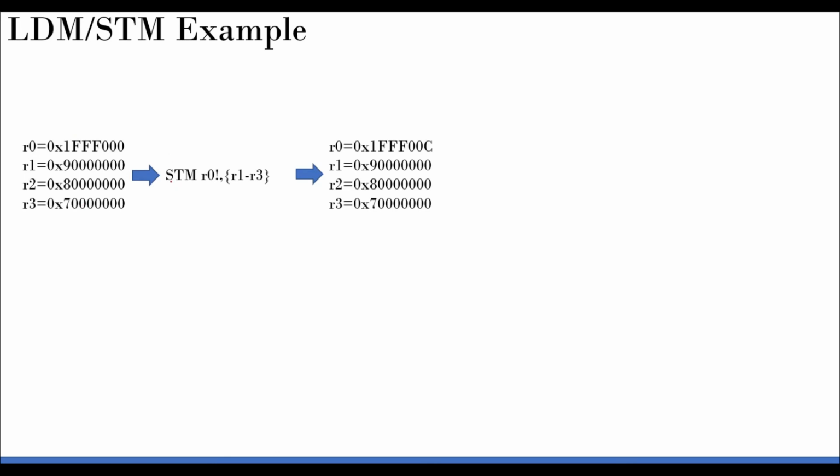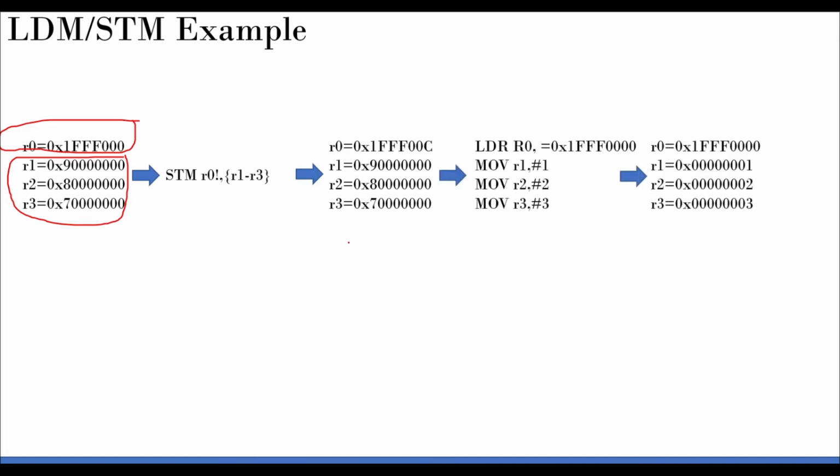And then if I do this, R0, this R1 to R3, so R0 is the address location. Okay, this is the memory address location. So what I'm going to literally do is put into this location the contents in R1 to R3. So all these 3 contents will be put into this particular address location. So after this, there is no change to R1, R2, R3 and R0, but in the memory location, if you see in the Keil, this memory location might have updated with these 3 register values. Okay, so that's the literal meaning of it.